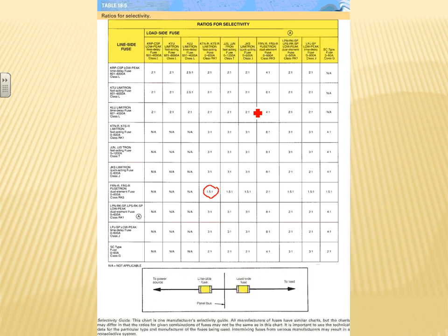So the easy thing to do is have two separate 200 amp feeds to your two elevators, then you don't have to worry about it. But as soon as you have one feed that goes to serve more than one elevator, you have to set it. A lot of people miss that requirement. It is a requirement regardless of what your occupancy is, hospital, whatever, any facility. You know, I've done 3 elevators.